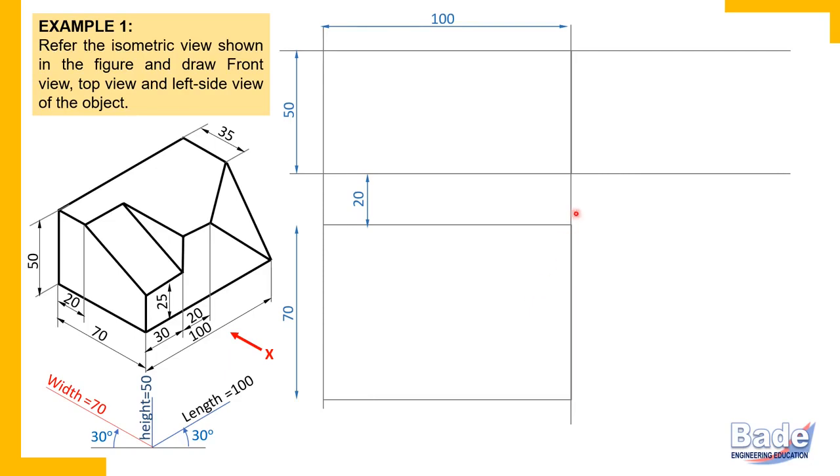This is very important to understand. I have seen many students take a lot of time to understand this, and that is why they make mistakes. Or even if they understand it properly, they forget it while drawing the actual diagram. So remember, in the side view, the two dimensions are height vertically and width horizontally.